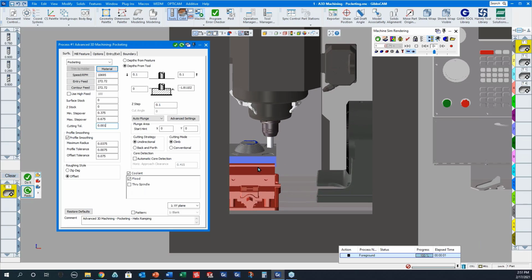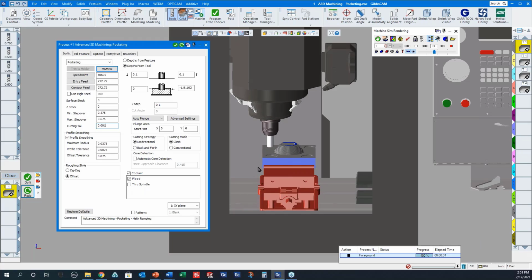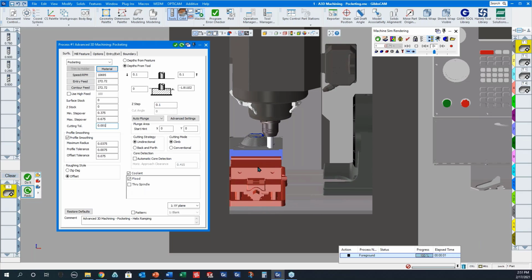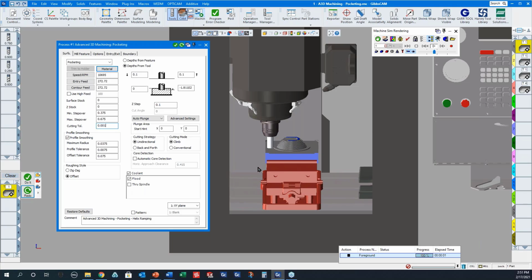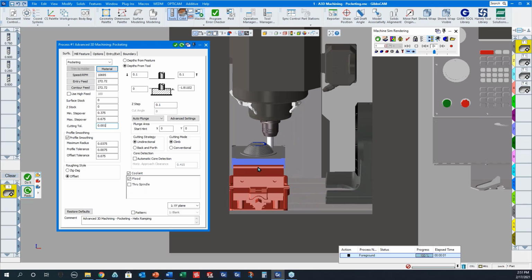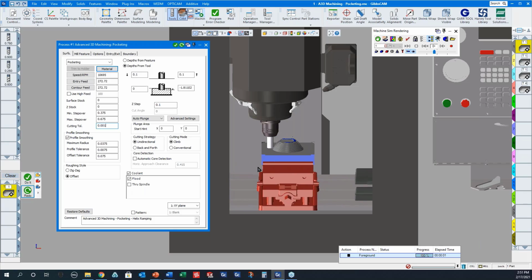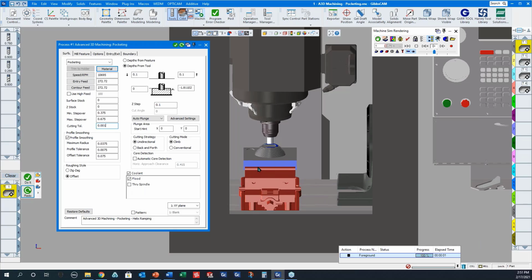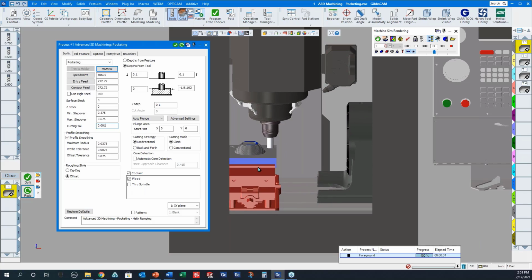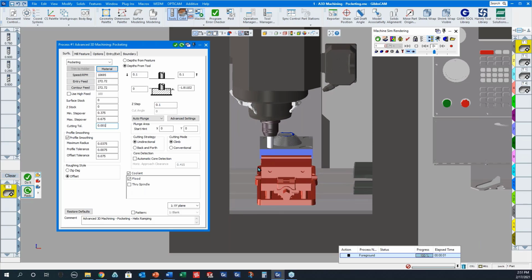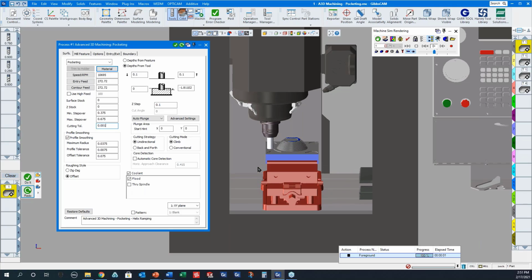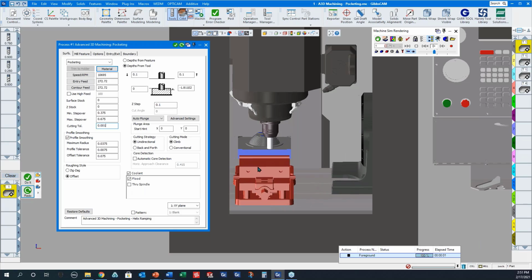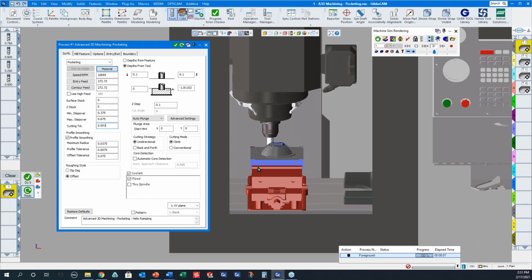That's generally it, and the other thing is using the surface flow cut in surface machining allows you to cut, as we saw in the example, fillets that lie end to end in a continual motion without having to use curve geometry. There's no process you can do that with in Advanced 3D machining without using geometry.